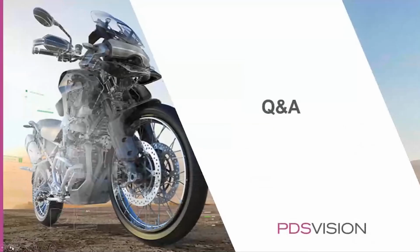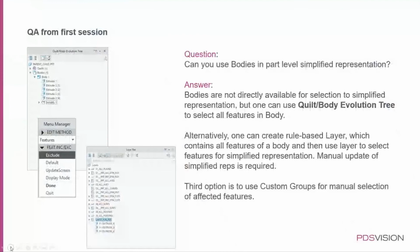Now, that was this last slide. Last time I promised to get back to you on one of the questions from the audience: can I use bodies in simplified reps? And the answer is, well, no, not directly still, unfortunately. But what you can do is, we have this quilt body evaluation tree, where you look at one of your bodies, let's say like this. In here you have body number 1, and then when you come to creating a part level simplified rep, you just exclude and pick all of them from here, and you get your simplified representation, which basically removes all of the features for that one particular body, resulting in 0 objects for that.